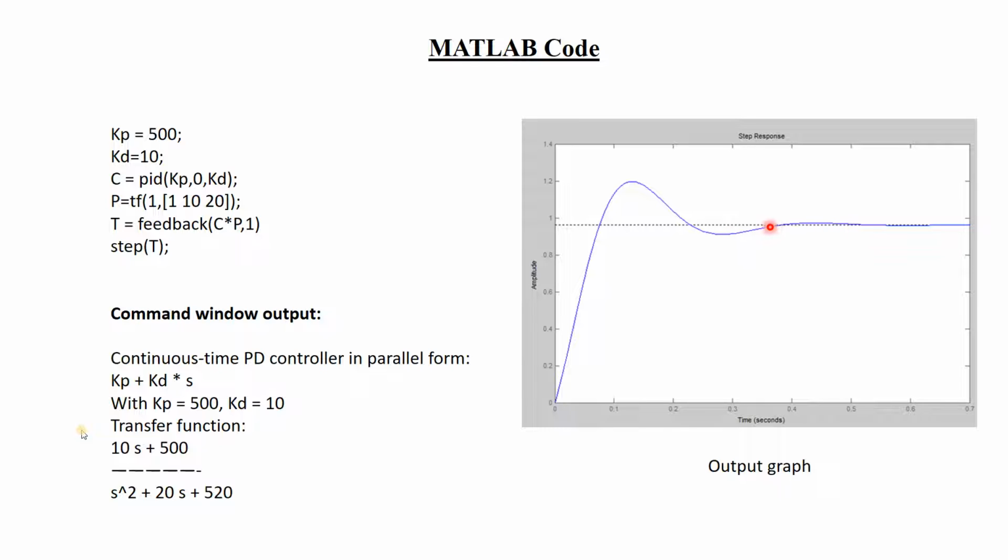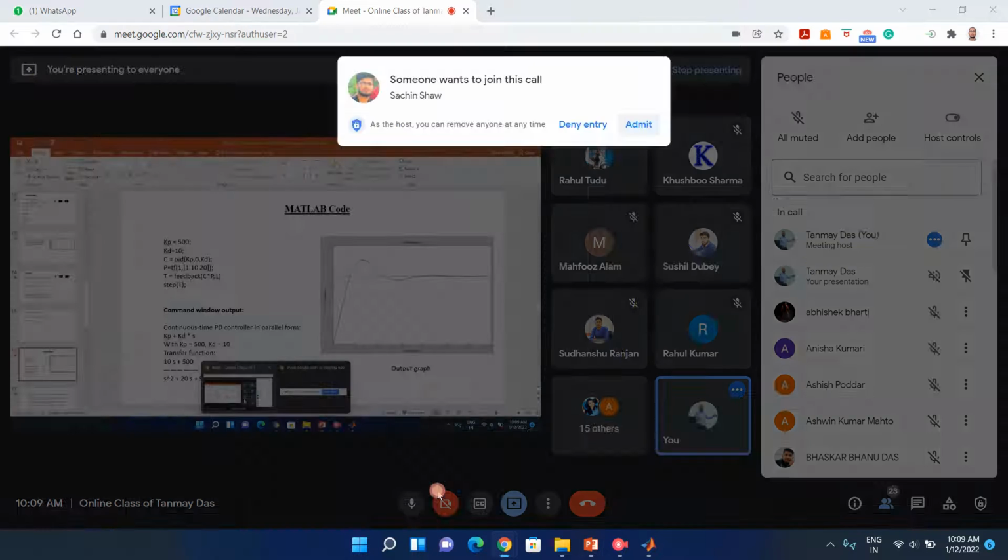The overshoot was reduced, the oscillation was damped and the settling time was reduced, but the steady state error was not 0.